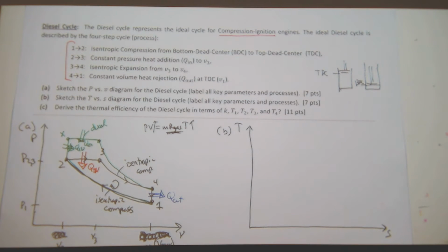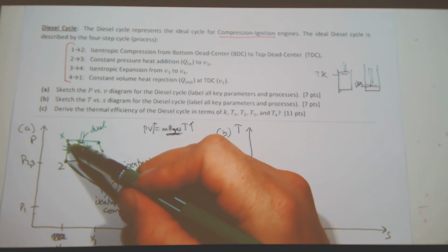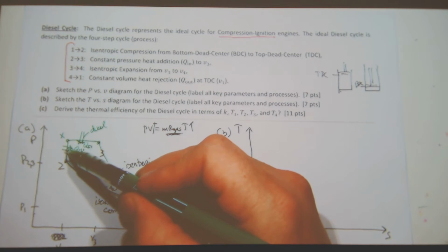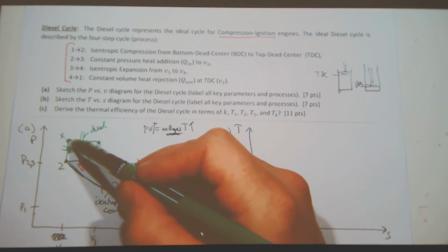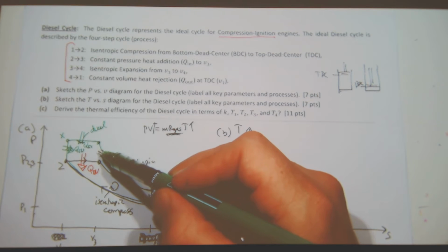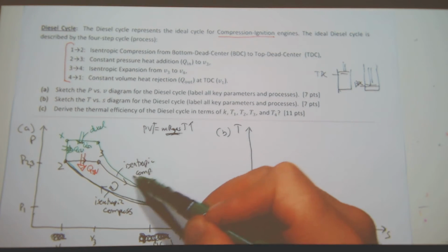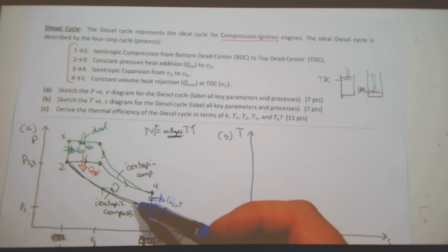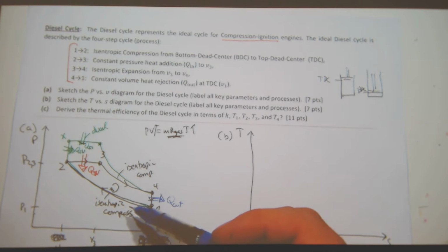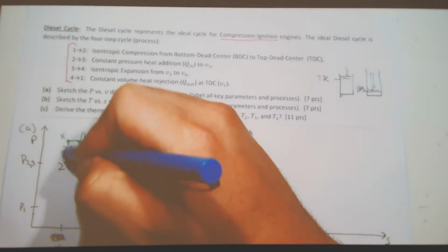And you can kind of see here, now when I get auto ignition, I get an increase in temperature and pressure, and a really quick one such that there's no change in volume, and then I get additional heat in, and then the rest of the power stroke, which can be looked at as isentropic expansion. Now, I'll put on here in blue what the real diesel cycle looks like, and it looks something like this.